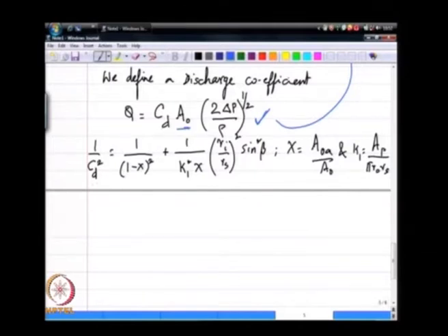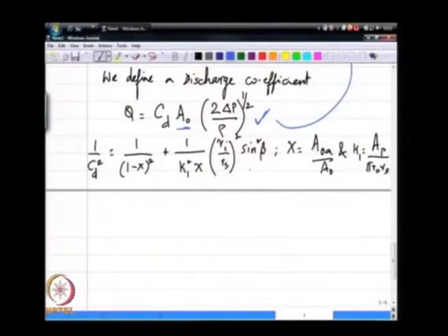So, if I have a CD, I still have only one expression down here coming from our Bernoulli's equation, which relates K1 and X. X is still something we have no handle over, that is determined by the fluid mechanics inside the atomizer. Apart from of course R_i over R_s and sin beta, these are all also design variables, degrees of freedom that are available to us, and we have only one expression. So, herein comes a simple principle that is often invoked to fix the value of X.